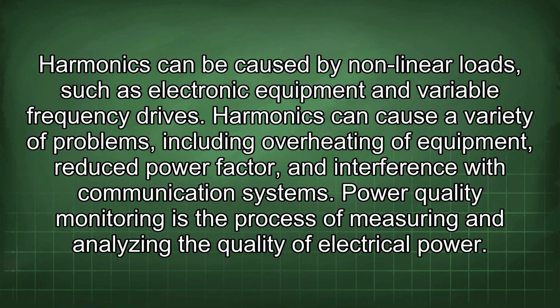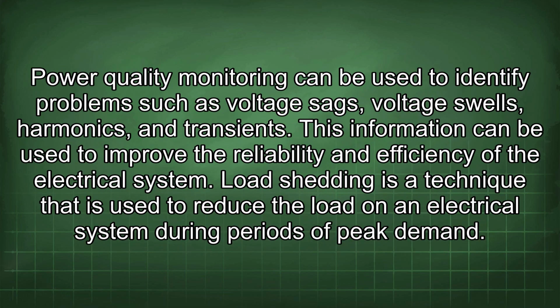Power quality monitoring is the process of measuring and analyzing the quality of electrical power. Power quality monitoring can be used to identify problems such as voltage sags, voltage swells, harmonics, and transients. This information can be used to improve the reliability and efficiency of the electrical system.